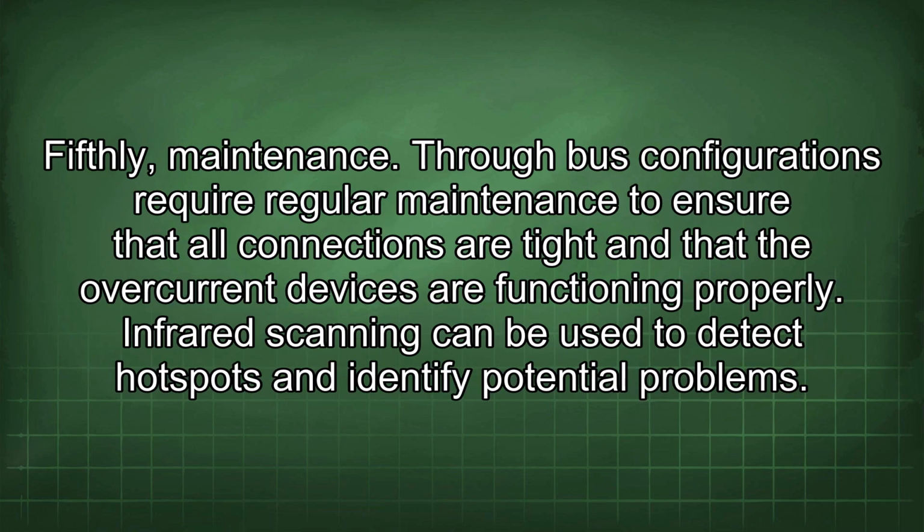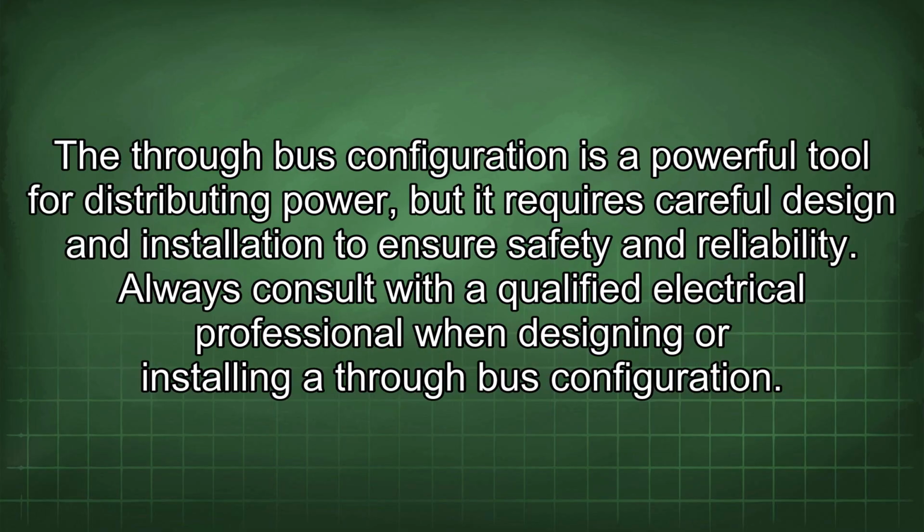Fifthly, maintenance. Through-bus configurations require regular maintenance to ensure that all connections are tight and that the overcurrent devices are functioning properly. Infrared scanning can be used to detect hotspots and identify potential problems. The through-bus configuration is a powerful tool for distributing power, but it requires careful design and installation to ensure safety and reliability. Always consult with a qualified electrical professional when designing or installing a through-bus configuration.